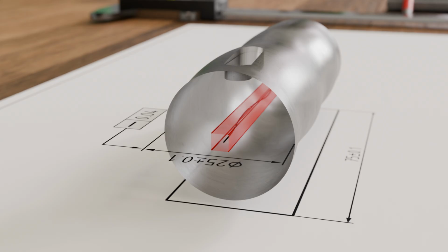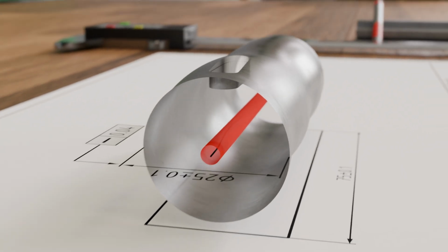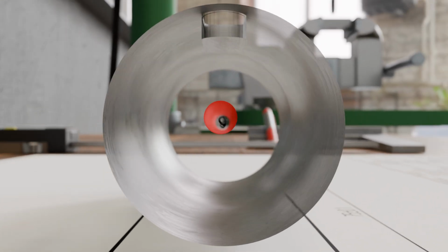A much more meaningful approach here is a cylindrical tolerance zone, which is also rotationally symmetric according to the shape of the part. We no longer talk about two parallel lines at a distance of 0.04 mm, but rather about a tolerance cylinder with a diameter of 0.04 millimeters, within which the shaft axis must lie. If this condition is met, the shaft axis is considered straight in terms of the form tolerance.